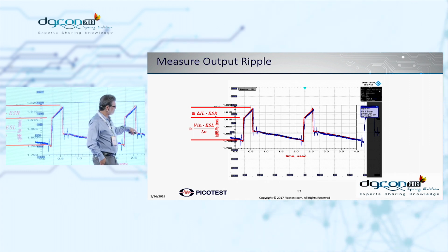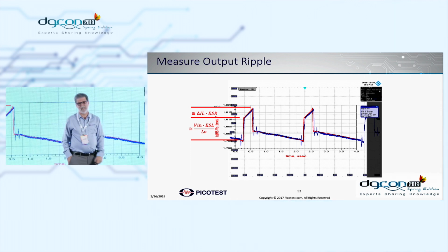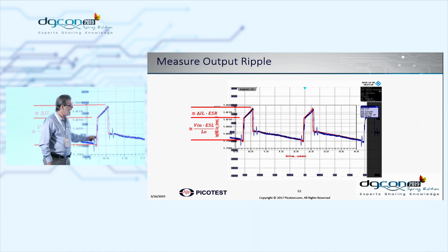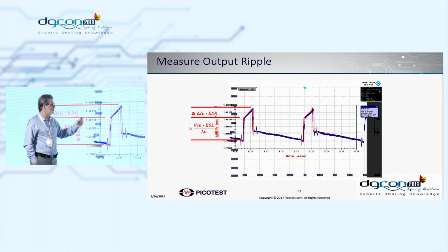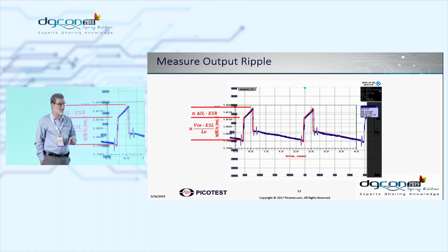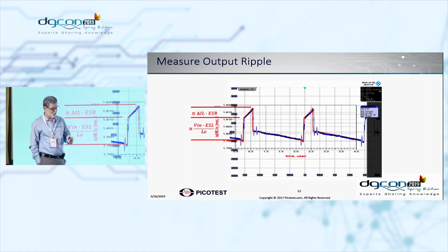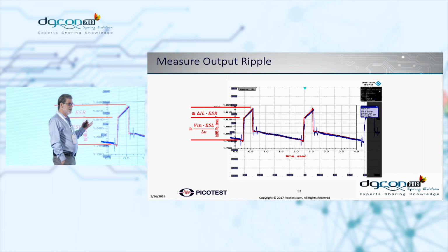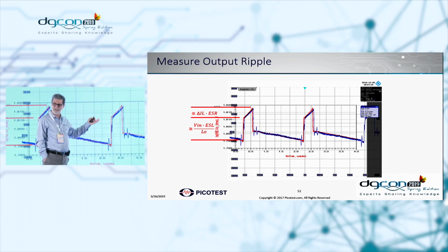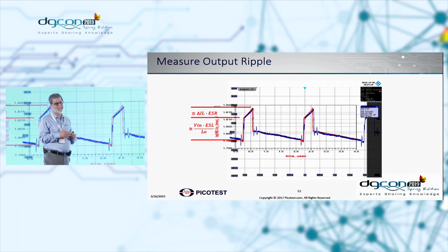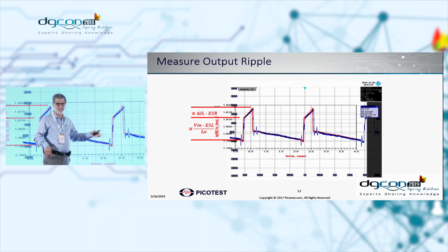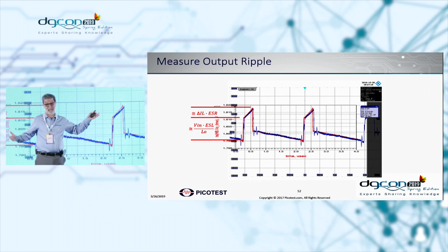These little blips are the switch times from the internal MOSFET gate driver, which isn't in my model. Certainly I could include that. I could even include the circuit board and it would be an even better reconstruction, but you've got to admit, that's actually not a bad picture of the ripple. It's got good fidelity. When we put this into a power distribution network, this noise is one of the largest noise sources. In the Xilinx case, one of the things I had to trade off were efficiency, switching ripple, and impedance.